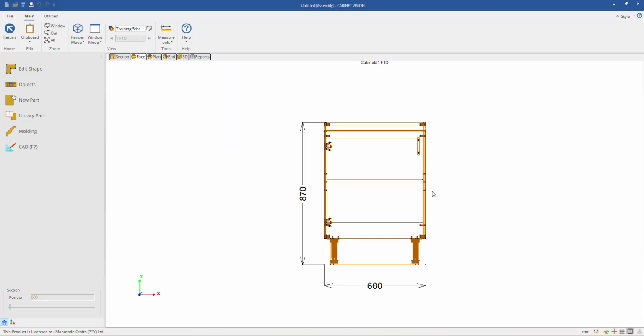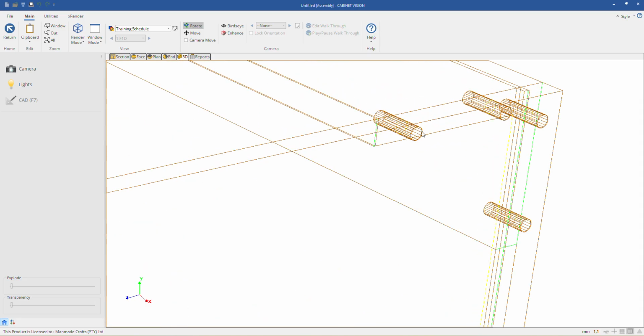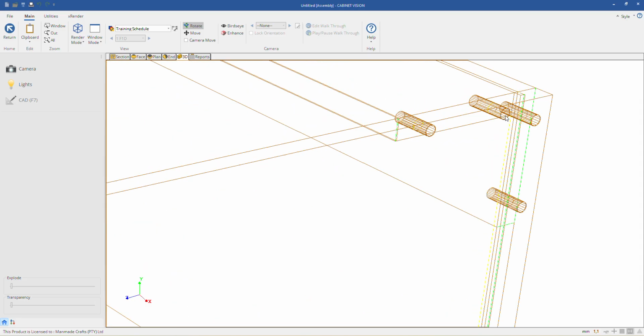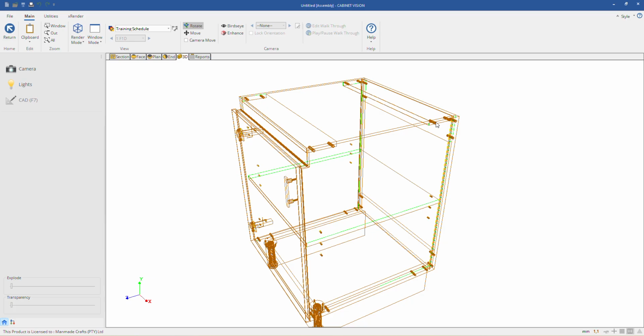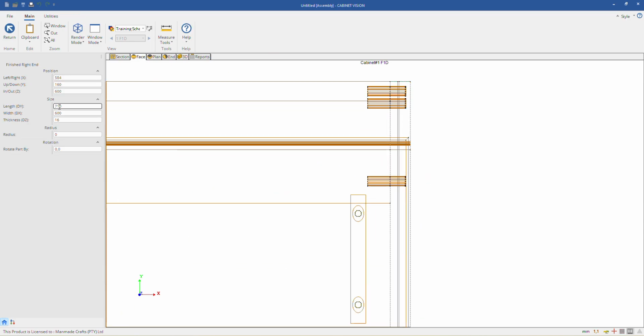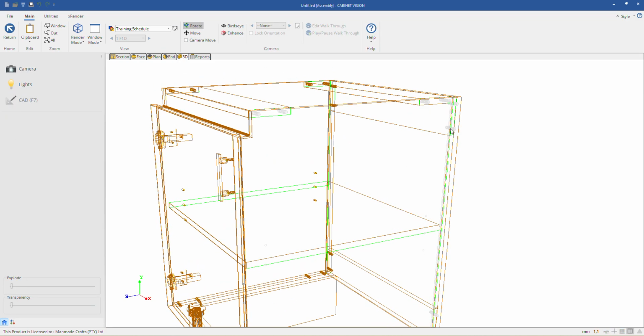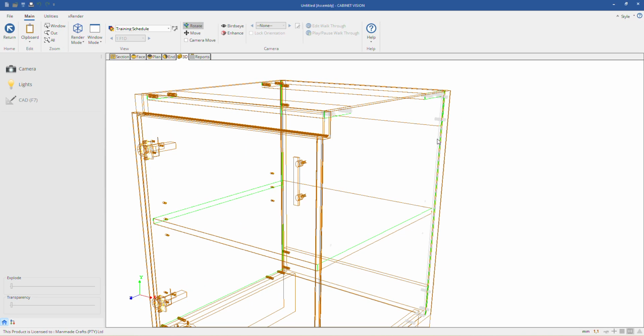Watch what happens. I'm just going to go into this unit and go to render mode. You'll see how my connections show red. As soon as that machining is not firing, so let me do this. I'm just going to change that quickly to 585 and move it away. See what happened? It went gray, which means that's an unmatched operation. Those holes aren't going to machine. It's not going to fire. It's unmachinable. There's a gap or there's an issue.